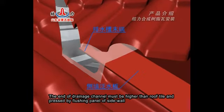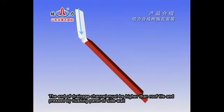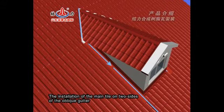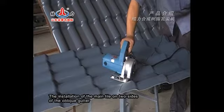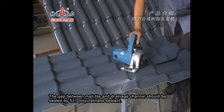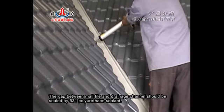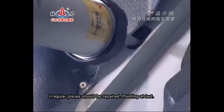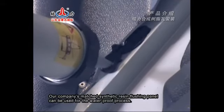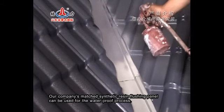The end of the drainage channel must be higher than the roof tile and pressed by the flushing panel of the side wall, in order to connect the oblique gutter and flushing panel or eave gutter. The main tile on two sides of the oblique gutter should be cut carefully according to the shape of the drainage channel. The gap between male tile and drainage channel should be sealed by 531 polyurethane sealant. Irregular places should be repaired. Painting at last.